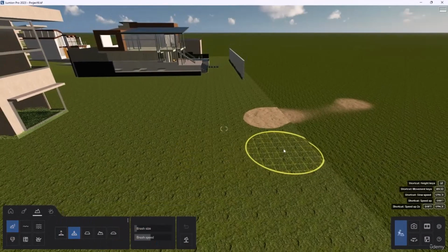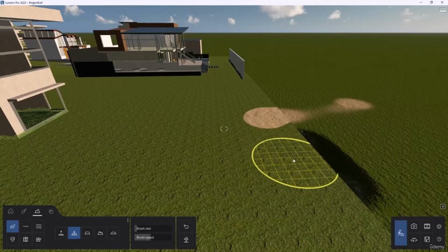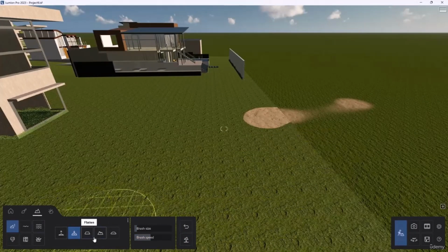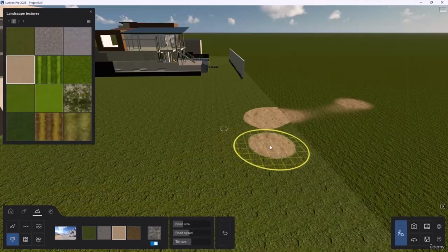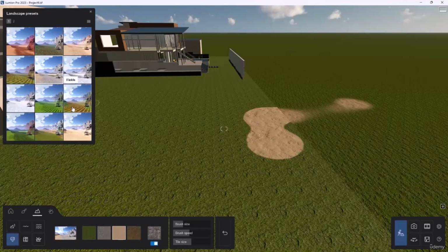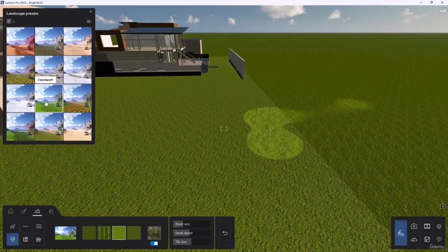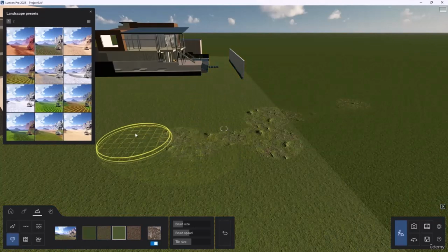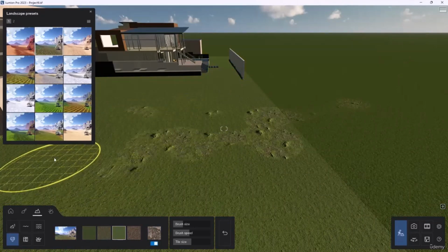Very good. You cannot use rise or flatten or smoothen or jitter for this landscape, since its geometry is out of the software. The geometry is out of Lumion. But you can use paint or these structures that we have here. As you click here, see, it affects it.